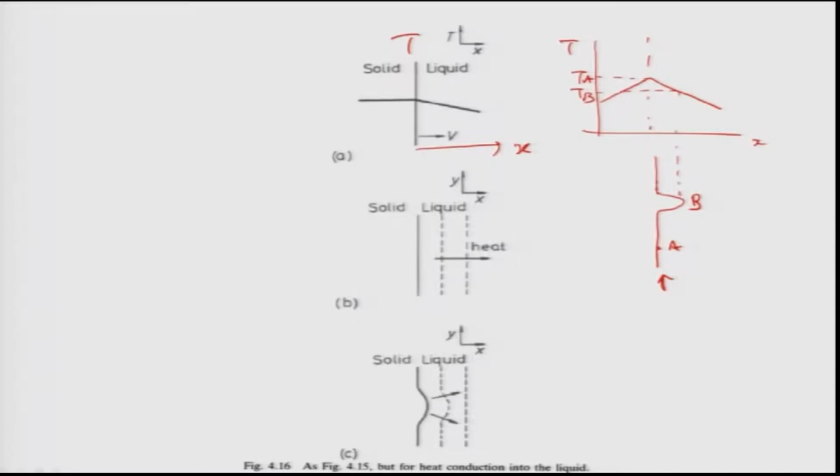Fine. So, what you see here very clearly is that, because of the negative temperature gradient in the liquid, the point B temperature TB is less than TA, and therefore point B is undercooled more than point A, because undercooling is again defined as Tm minus T. Now, as TB is lower than TA, the total undercooling delta T is higher at point B than at A. As B is getting undercooled more than A, B will have more driving force to grow.